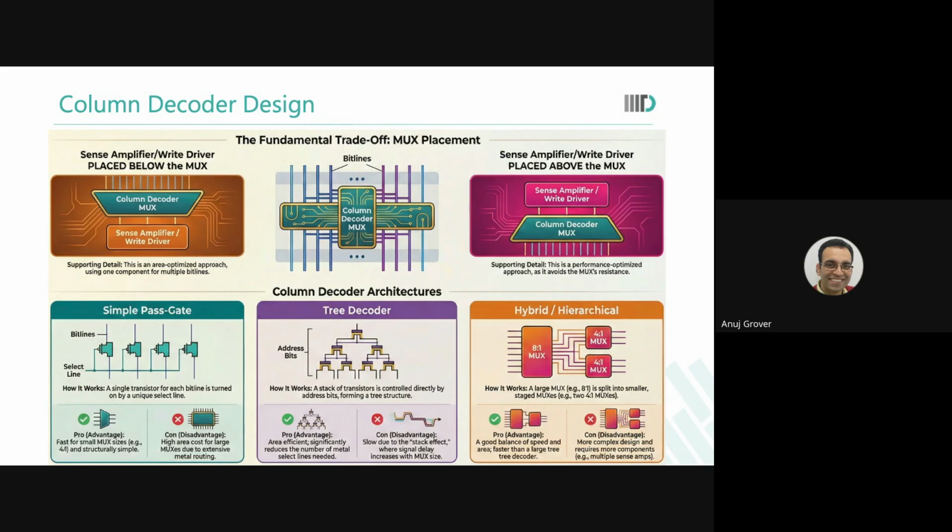Sir, in the previous class we talked about this mechanism in which we do selective pre-charge off. We don't do pre-charge off for the entire array. So in that case, would the column decoder design become more complex, because then you have to control the pre-charge also? Madhav is asking that when you have to do selective precharge, that is, non-selected columns will have their precharge on, does the column decoding architecture become more complex?